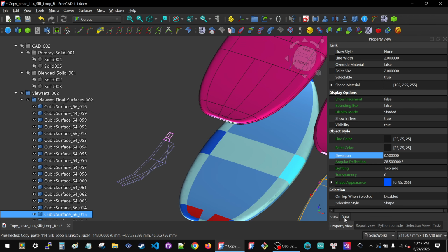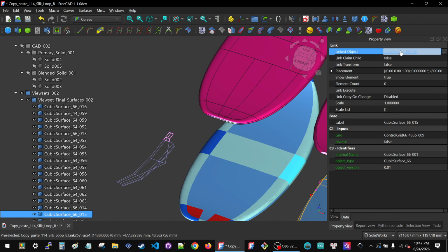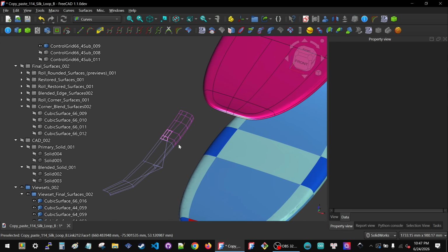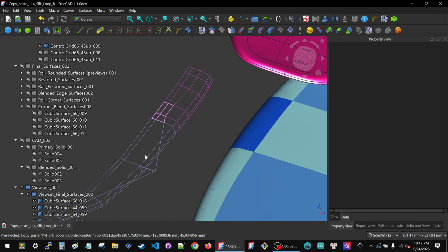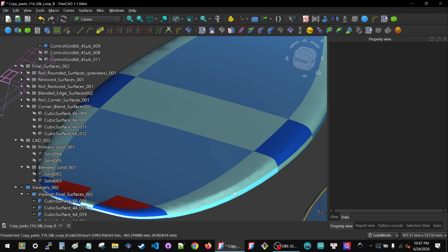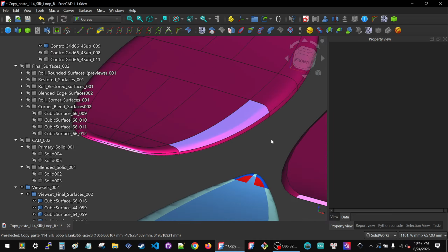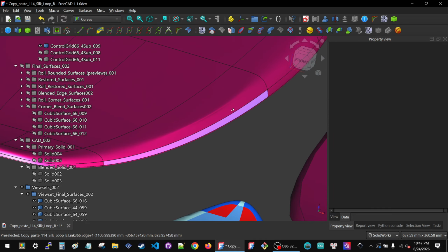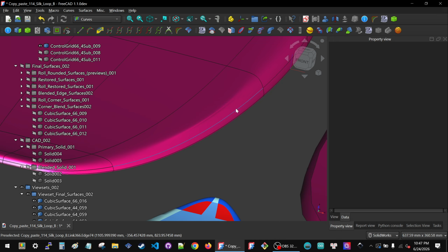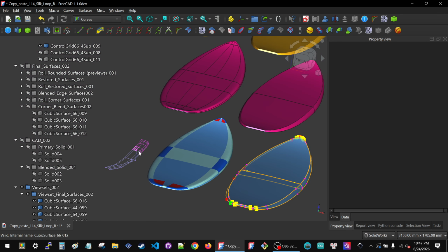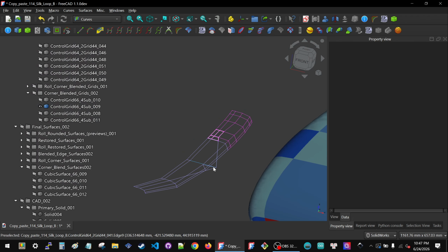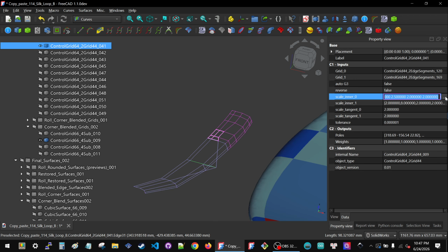And it's pushing this really odd angle into this guy's grid. Let me find that guy's grid. It's in view. It's a cubic surface, which comes from here. Here's its grid. All right, see, this wild line right here doesn't do anything so horrible within the blend itself. I mean, it does cause a ripple, but it's pushing weird stuff into the corner subgrid, which then means that my double blend has some weird stuff in it.